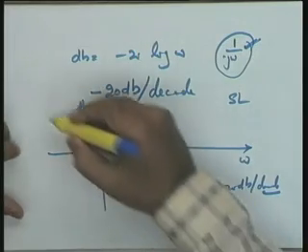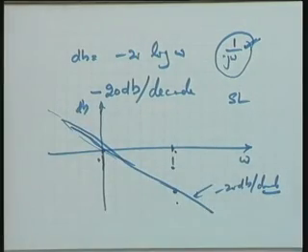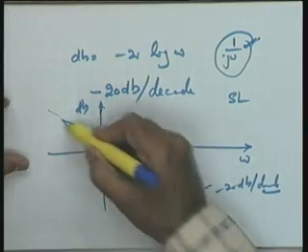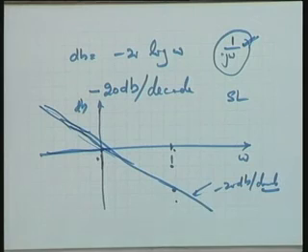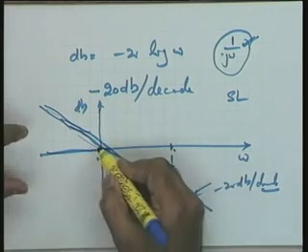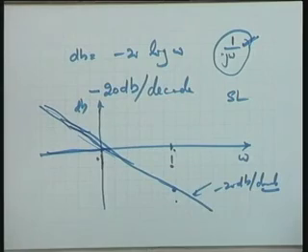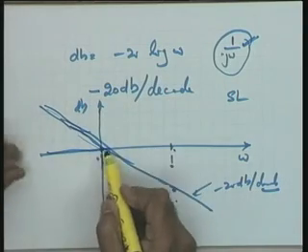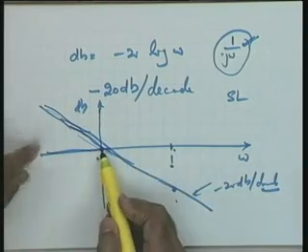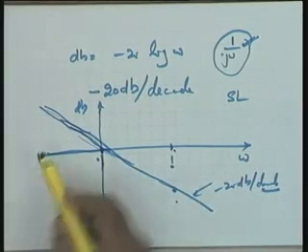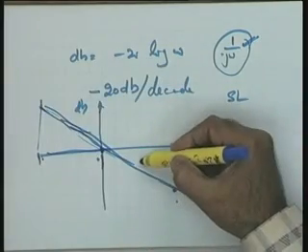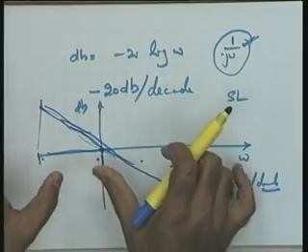You see that we have a line now, and this line is effective in the entire region. Why it should be shifted up is that it is going to be effective for frequencies lower than 0.1 as well. Sorry, at 0.1, equivalently, if you have a paper here, you take a decade of frequencies here and just take 20 here. It depends on the decade you want on the semi log paper.